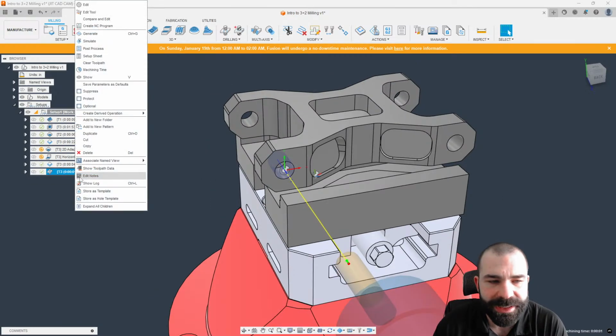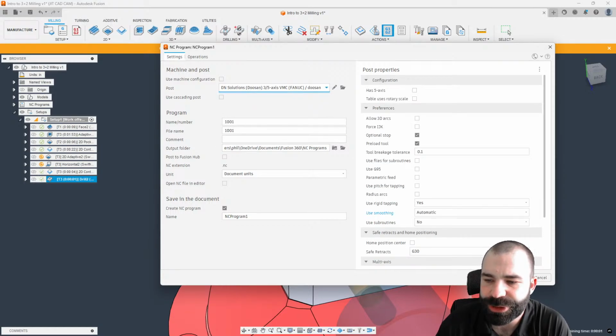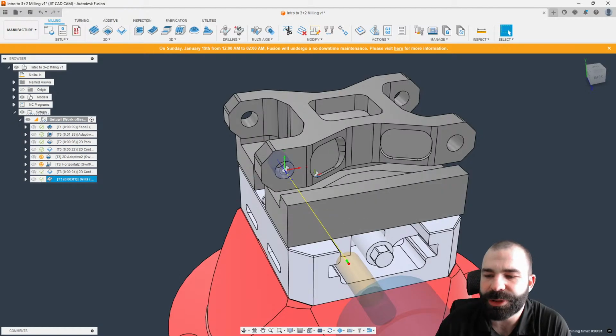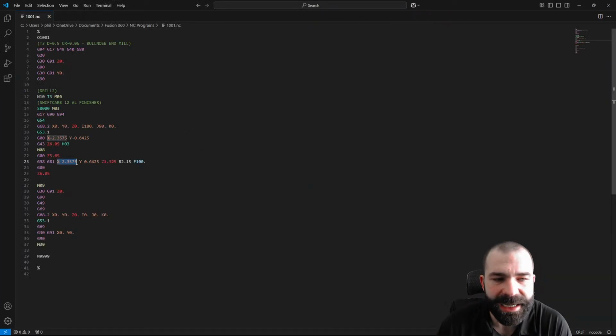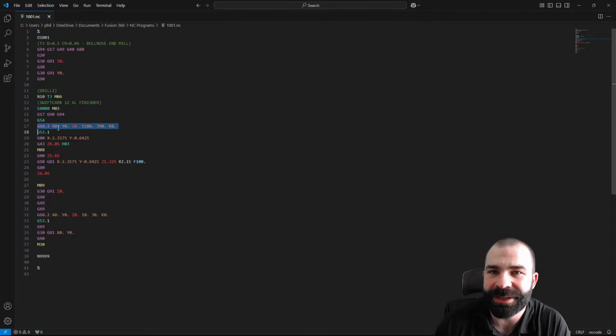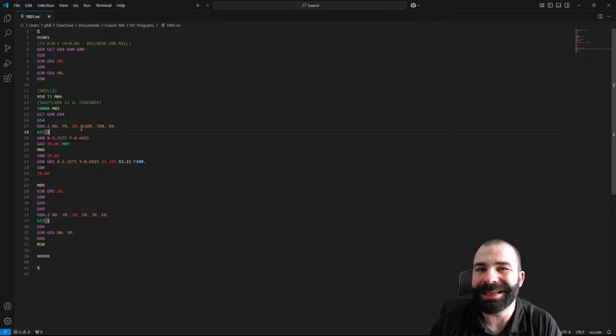Again, when we post this out on something like a Fanuc post or a Siemens post, we go ahead with this DN Solutions post. And we got to make sure that we do have 68.2 turned on. It is going to provide the shift in X, Y, and Z. So what actually is happening here, oh, we're looking at the wrong thing. I apologize. So we have our tilted planes happening, but there is no X, Y, and Z shift. We can force an X, Y, and Z shift if you want to see where that exact location is, or if you're machining something from datums, of course. But as you're seeing, where that actual origin is sitting when we use a joint origin doesn't really matter, because this is all still coming from that center work offset on our part where we set this up.